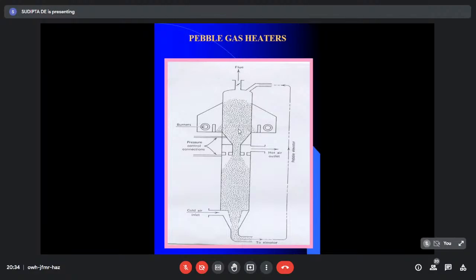And generally the surface texture, meaning the outside surface, how it is, also affects the heat transfer characteristics, improving the heat transfer coefficient. And your answer is right in a sense that the heat transfer coefficient has to be increased somehow. But the heat transfer coefficient itself will increase if you can make it a favorable heat transfer condition. But the heat content, how much heat is within these pebbles, matters, because if it doesn't have sufficient heat, when the temperature difference is tending to a small value, not zero, but a small value, then heat transfer will automatically stop. But before that, if it doesn't have a significant amount of heat, it cannot transfer a large amount of heat either.